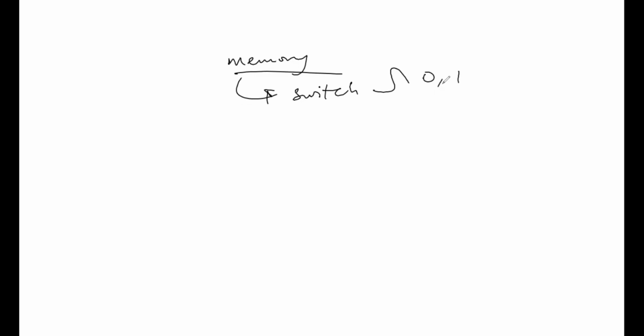Like we know that the Pentium can address up to 4 gigabytes, which is 2 to the power of 32 bytes of main memory, okay? So that is, the address bus of the Pentium has 32 address lines. That's what it means. So the number is referred to as the memory address space.